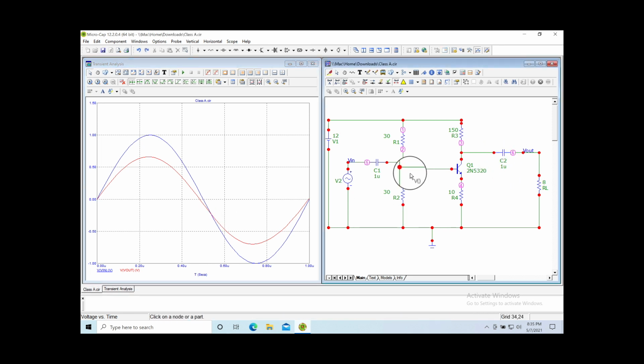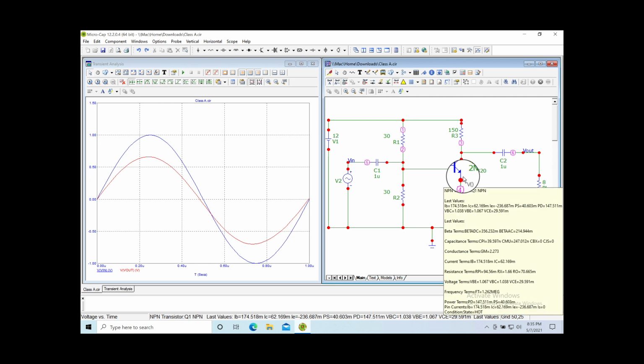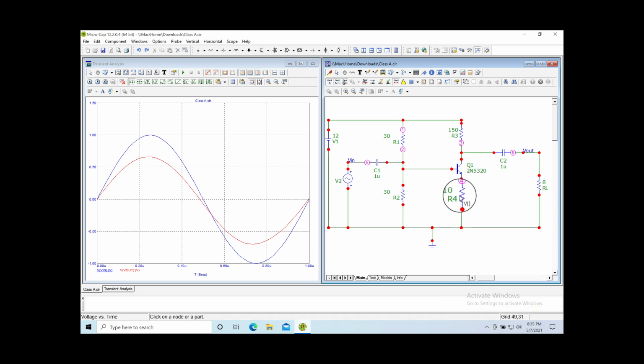Okay, I want to show you something that maybe you've already spotted, but it's just another thing to think about. Now, to turn on a transistor, you need to put 0.7 volts there, right? Well, remember we're biasing this up around 6 volts. When you think about that, you've got 6 volts here, 5.3. You've got a lot of current that's going to go through this resistor.